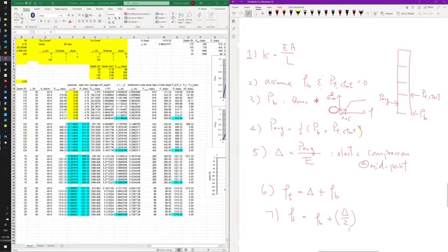We want to calculate the settlement at the middle now. We calculate the settlement at the top, and we also calculate the settlement at the middle, which will be equal to the base settlement plus half of the elastic compression settlement. So that's the settlement at the midpoint.